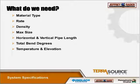Temperature and elevation are very important. It's going to affect the air density. As an example, air at 2,000 feet is going to be 7% thinner than at sea level, and air at 100 degrees Fahrenheit is about 5% thinner than at 70 degrees Fahrenheit. If you don't take this into account, your system might operate in the morning, but then not in the afternoon when it heats up. So at Jeffrey Rader, we always make sure that that is accounted for.